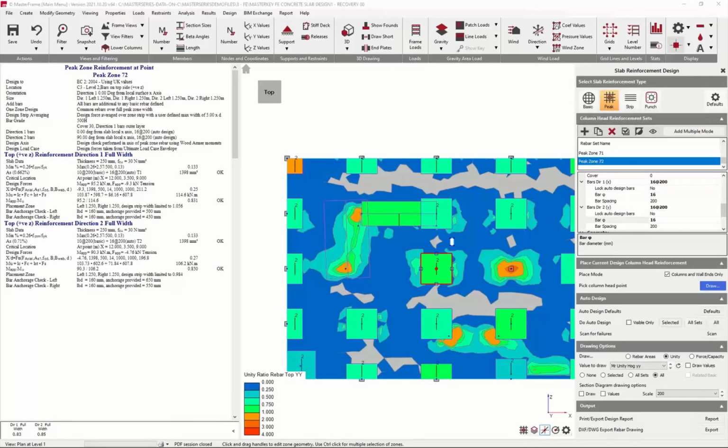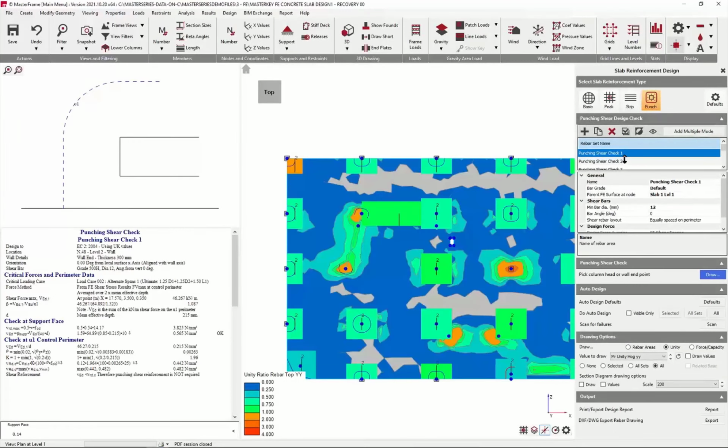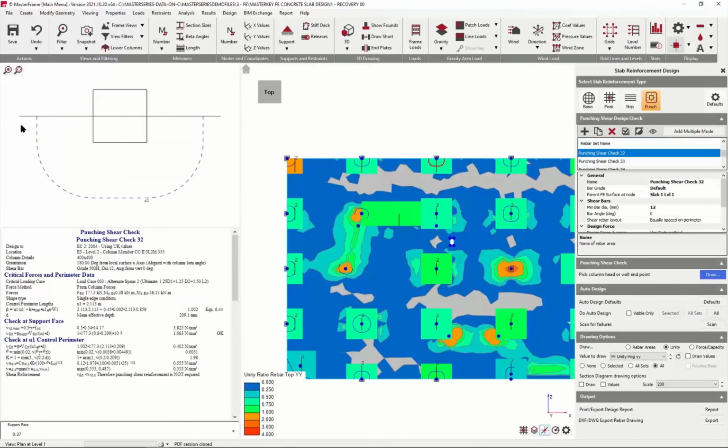Columns are at the edge of a slab. Does punching shear take account of the full width of the column? It will take account of most things. If I go to punching and I look at, say, this one here, it's assuming it's a halfway, and most of the time it will show up to be fine. You know, if it's that little extra bit that's going to make it work, you're running pretty close to the wind. But certainly we are looking at allowing the program to include that overall area, even though it's analytically at the edge.